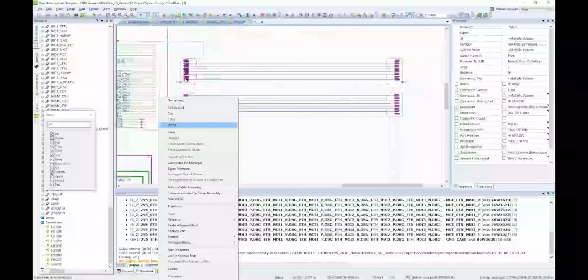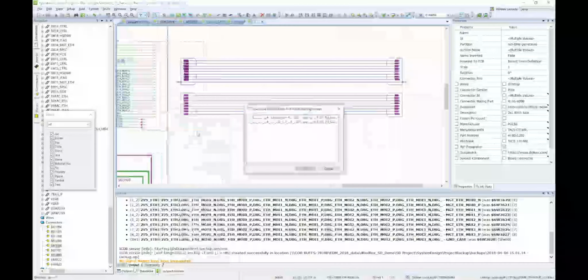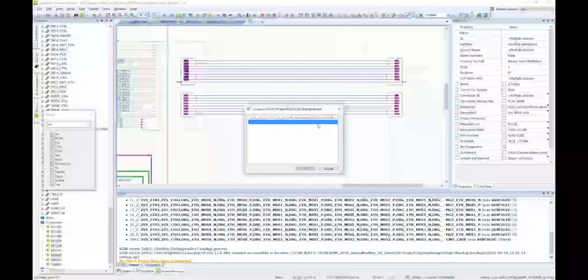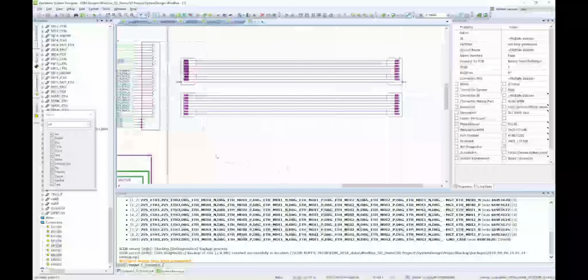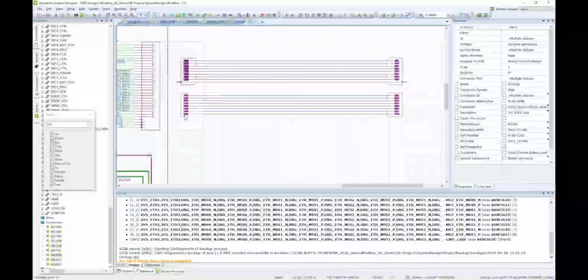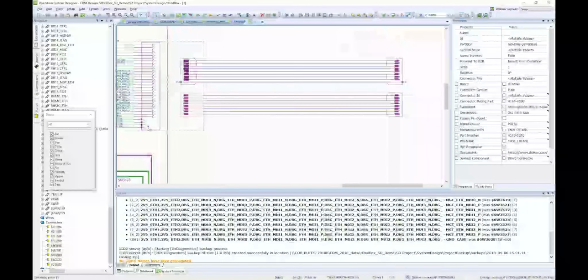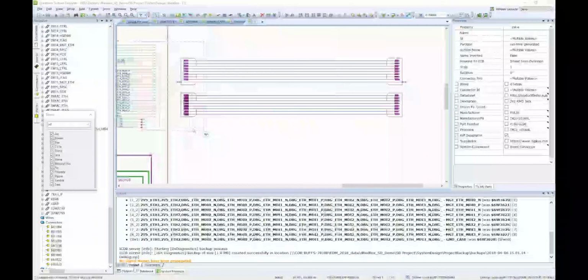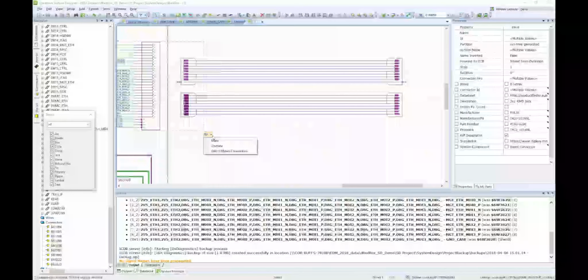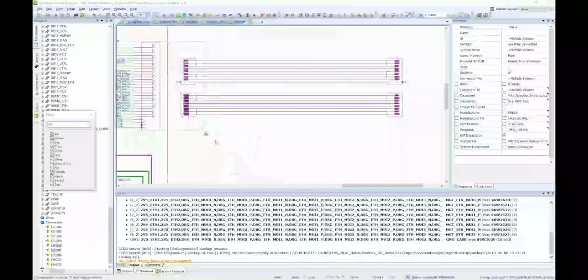Now that the cable has connectors and wires, we can mate the board mount connector to the cable connector to create a system. Select the board mount connector and the top cable connector, and the mating icon appears, or use the right mouse button to mate. There are two choices for mating, because the board mount connector has two slots.